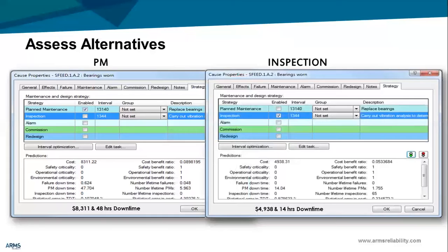And some of you may be thinking, well, of course, condition-based maintenance is always good. We just have to do an inspection. Well, the clever thing here is that I'm not just doing the inspection activity. Incorporated in that cost number is the cost to do 1.7 secondary actions, and that's defined by my Weibull distribution. So I'm budgeting not only for the primary activities, which are the inspections, but also for a secondary action, which is the replacement. We'll talk a little more about budgeting later in this webinar.